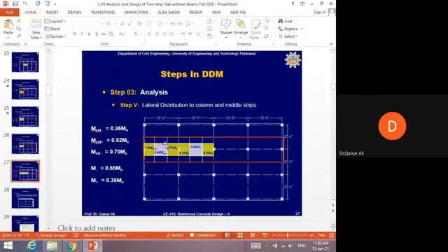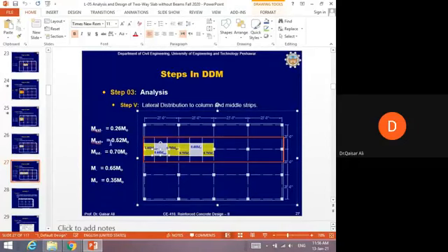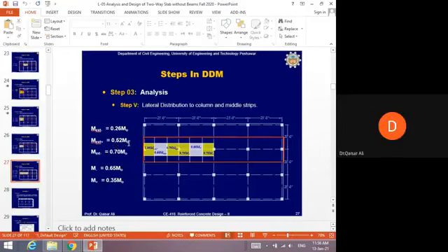For the positive bending moment, 60% will go to the column strip. 60% of this 0.52 M naught. When you find out M naught, the whole bending moment, then multiply by 0.52. 52% of M naught will go to this positive bending moment, and of this exterior positive bending moment, 60% will go to the column strip. For the coming...